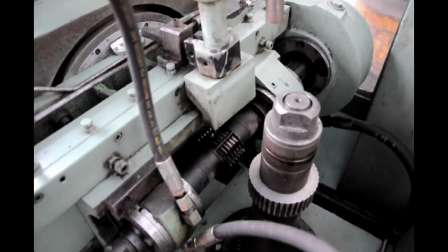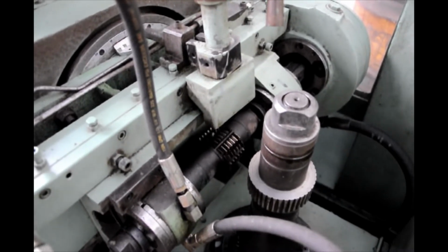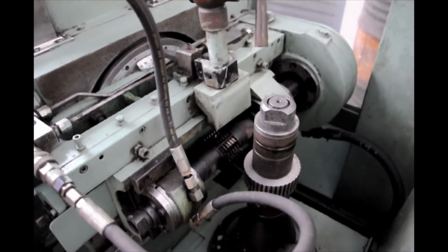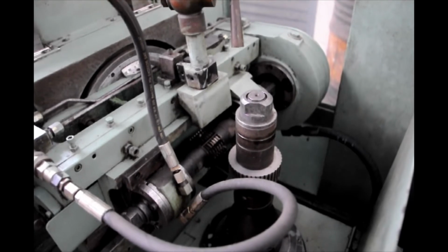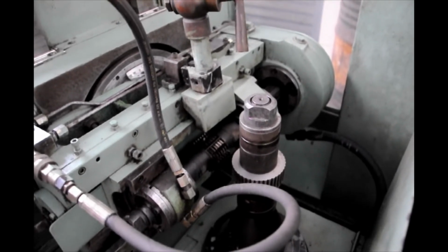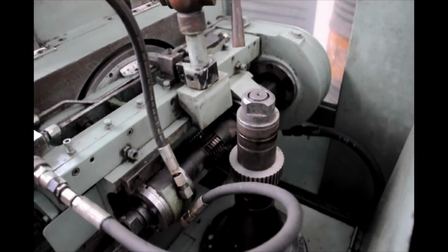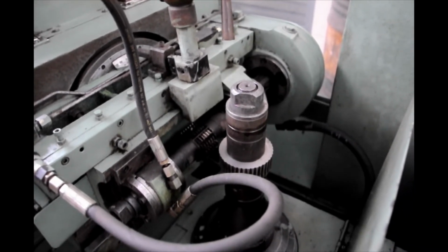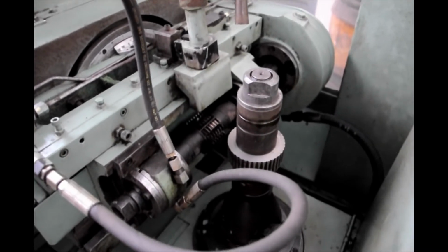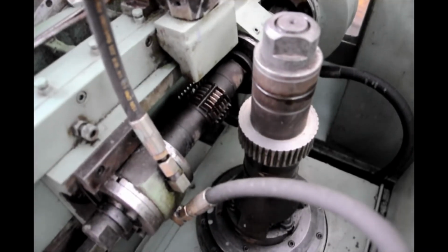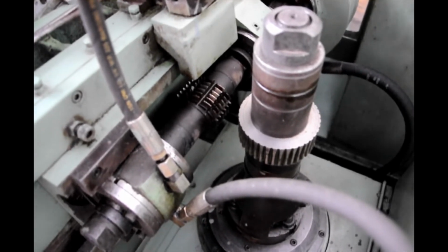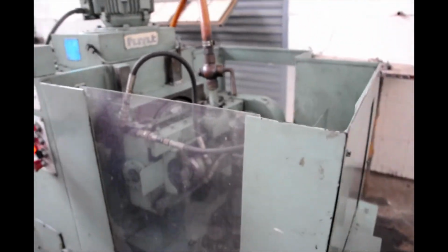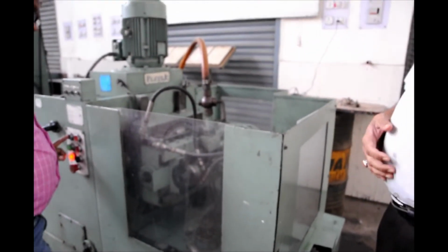A typical feature of a hob: the hob is again a powder metallurgy product, made of tungsten carbide, which is very hard, corrosion resistant and wear resistant. That is the specialty of the tungsten carbide hob. It is dedicated to mass production or large lot sizes, and in one setting it can produce many similar items, supplying automobiles that require huge numbers of similar gears, maybe helical gears, spur gears or spline shafts.